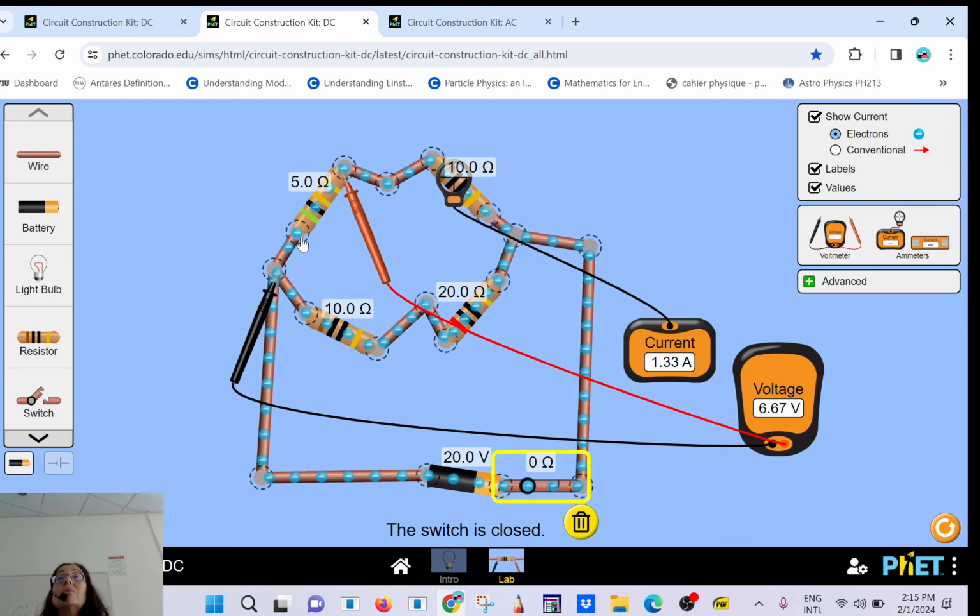So that's how much power is being stolen by this resistance inside, and that energy will be converted to heat. So it means that as the battery gets older, the resistance is going to increase, and your battery in your hand gets warm, because of that little resistance inside. Do you understand?